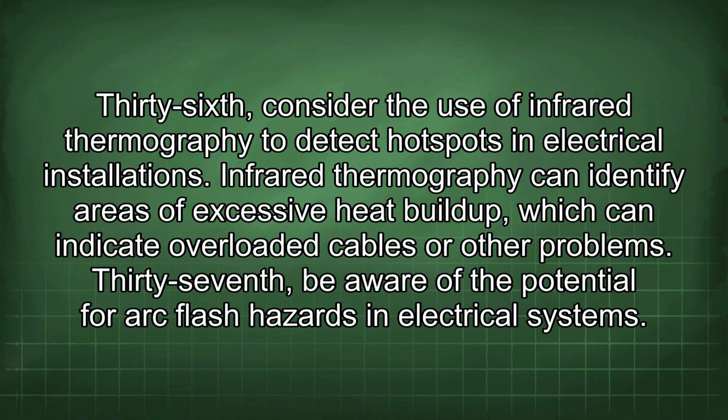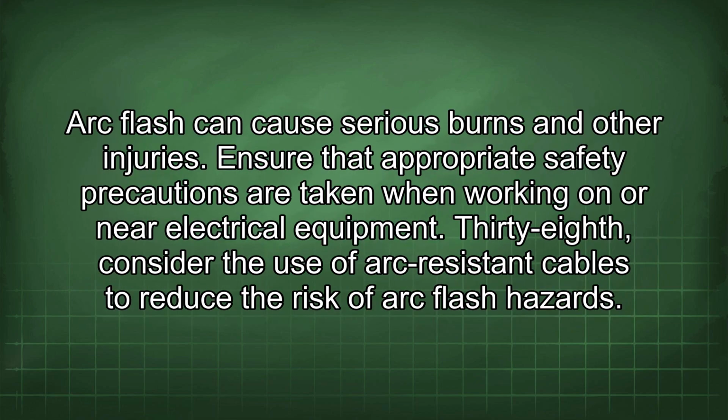36th, consider the use of infrared thermography to detect hotspots in electrical installations. Infrared thermography can identify areas of excessive heat buildup, which can indicate overloaded cables or other problems. 37th, be aware of the potential for arc flash hazards in electrical systems. Arc flash can cause serious burns and other injuries. Ensure that appropriate safety precautions are taken when working on or near electrical equipment.